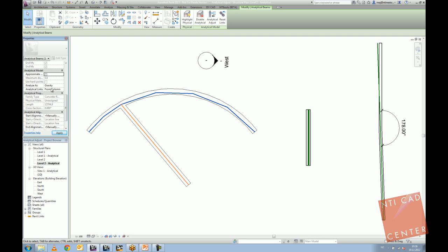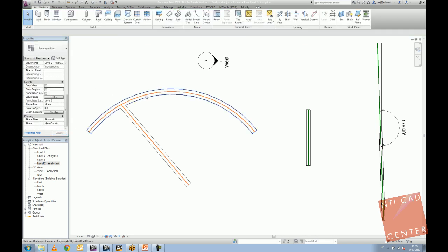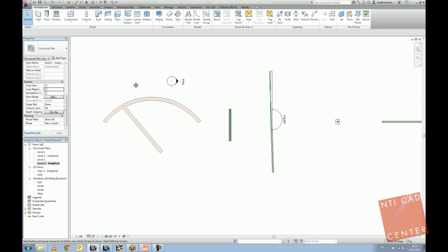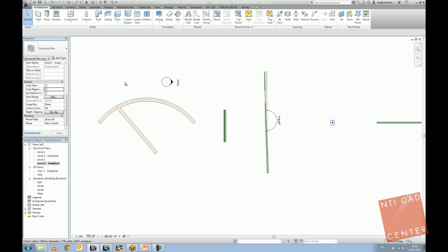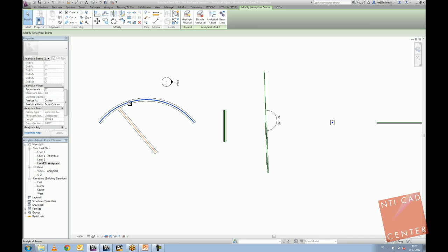Jumping out of this approximation, having straight elements. One thing I said I will mention is hosted elements, and this is a really nice feature. I will go into details about it a little bit later, but together with all of the modifications you can do with elements using properties, in most cases this is what you would like to do without messing with the analytical model. You would probably go to the properties and modify the analytical model there without actually dragging and dropping it.